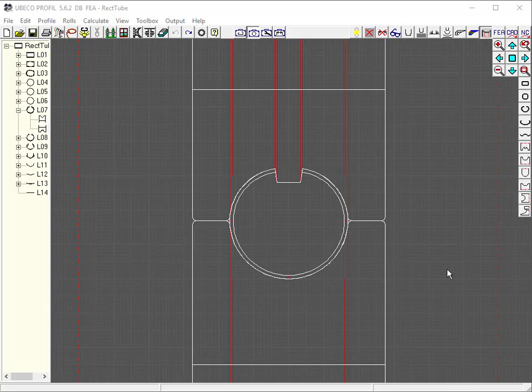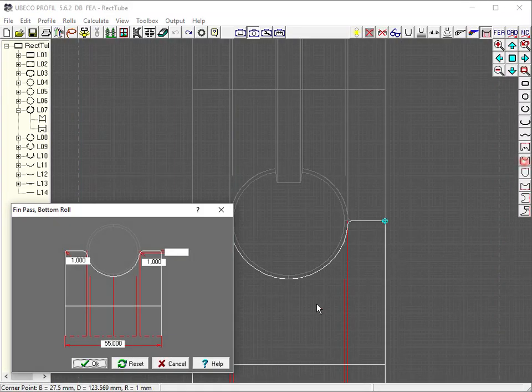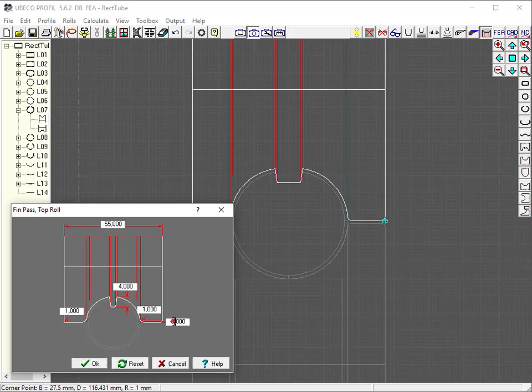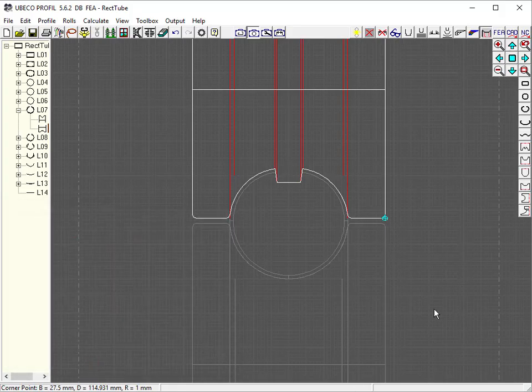Flange gap widths are generally based on a percentage of the thinnest gauge one anticipates the design to function with. If the material is low strength and the gap is too large, the material may extrude into the gap. With higher strength materials, the gap may be increased without creating a problem in forming.